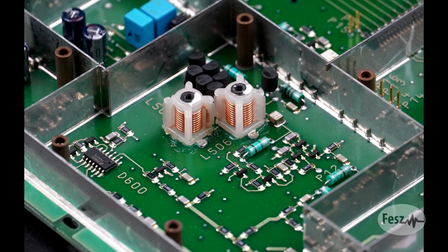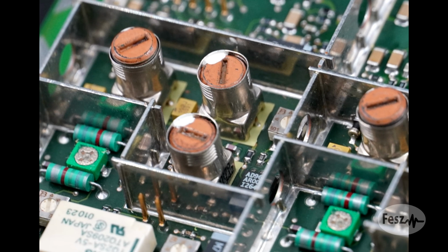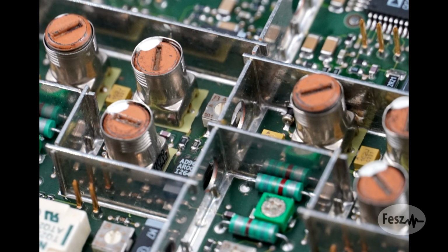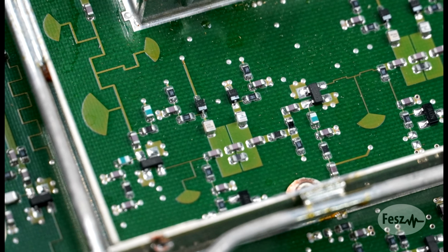Impedance matching is a complex topic with multiple possible implementations ranging from discrete components to transmission lines, the choice of which is usually done based on frequency and bandwidth requirements. Today, I want to look at a distributed element method which can be implemented as a wideband matching circuit, the stepped impedance transmission line transformer. So if you're curious, then keep watching.